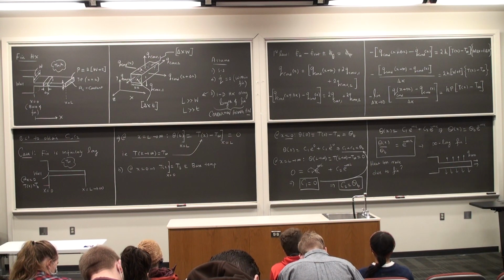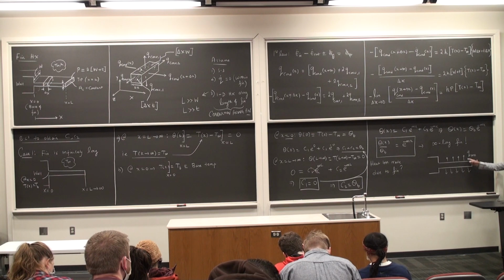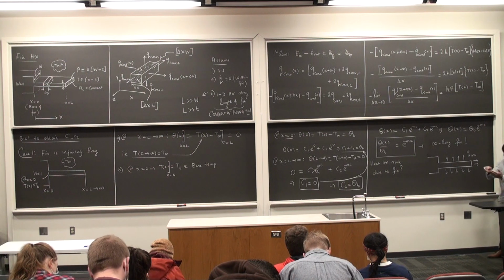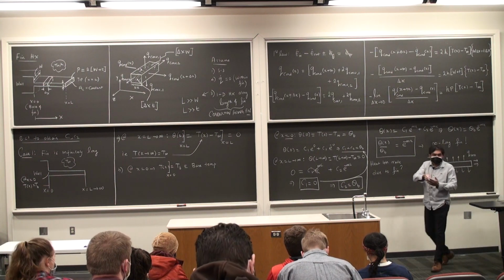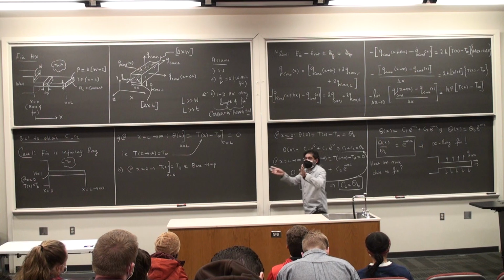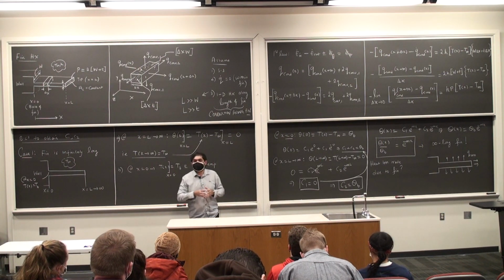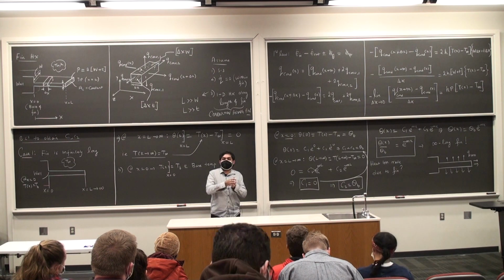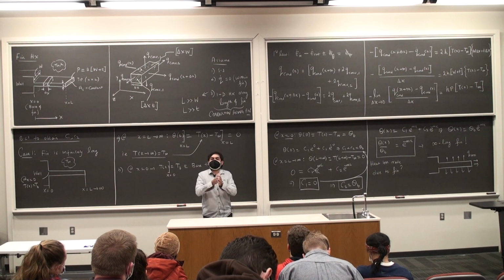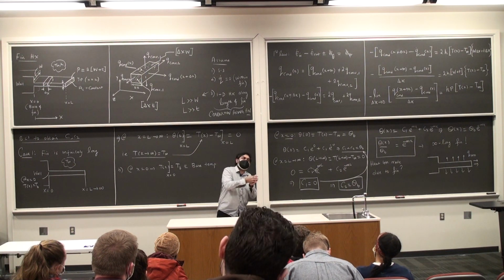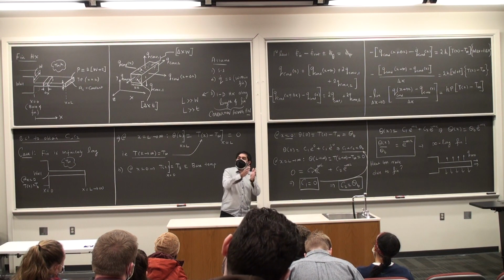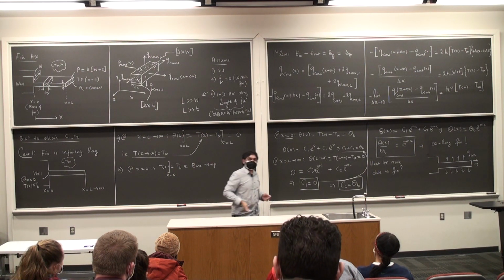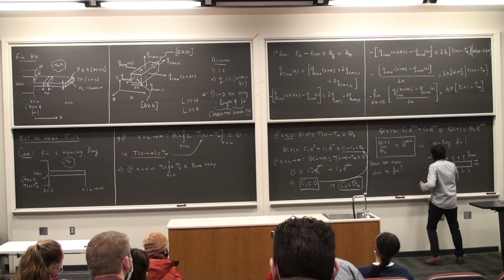The nice way to do this is the following. This is the heat loss rate which is coming out of the fin. Because there is no energy generation within the fin and because everything is at steady state, all the heat that is entering the fin has to be equal to all the heat that is leaving the fin. And all of the heat is entering the fin at the base of the fin, which means that the conductive heat transfer rate into the fin at its base should be equal to the heat loss rate due to convection on the surface of the fin. Okay, so here I'm going to say into the fin